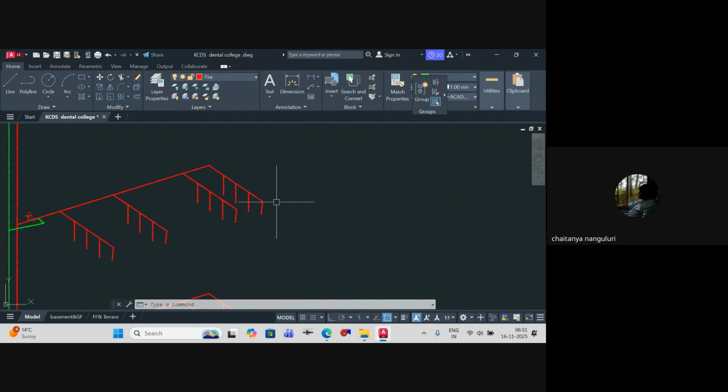Number two is, at many locations, for example, you might have given future tap-offs. Let's say from a builder's perspective, as a builder we have provided above-ceiling sprinklers. Below, I do not, because later the concessionaire will come, have a false ceiling, and plan his sprinklers. So when I do that exercise, I'll just provide roof sprinklers, and below that I'll just provide provisions. Then what should I do? They have to remove our sprinkler pipings and then we'll install your flexible pipes.